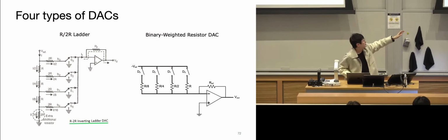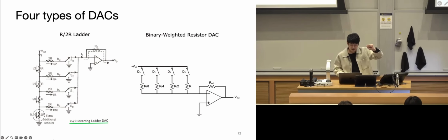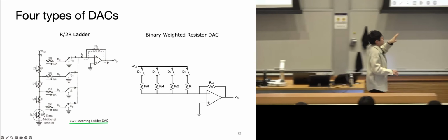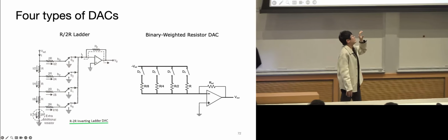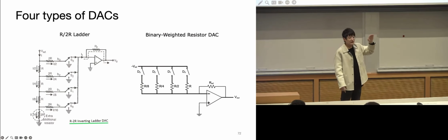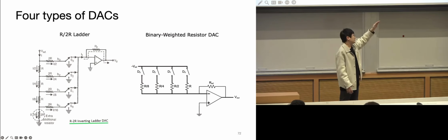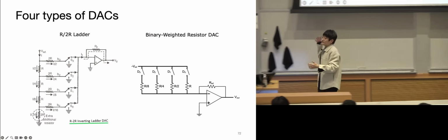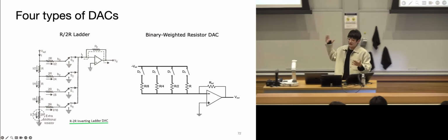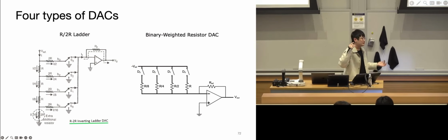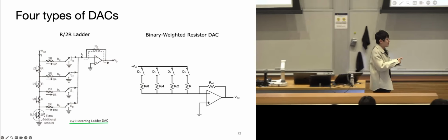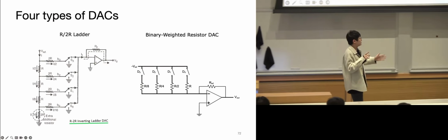And we also talked about the binary weighted resistor DAC. It's essentially using a series of resistors valued at a power of 2, either divided by 2, divided by 4, or times 2, times 4, and it depends on how many bits you want. One thing for that is, imagine if you have a very high bit DAC you want to do with this one.